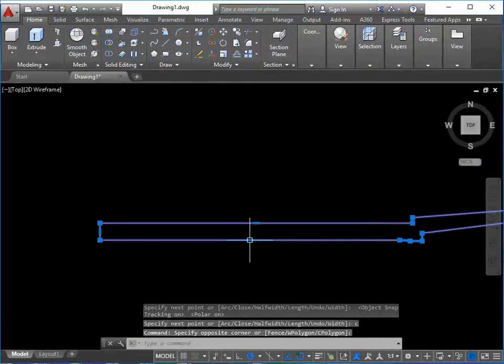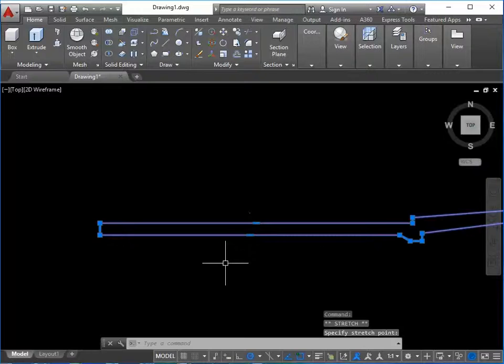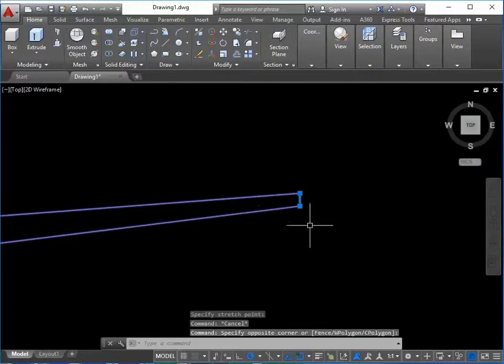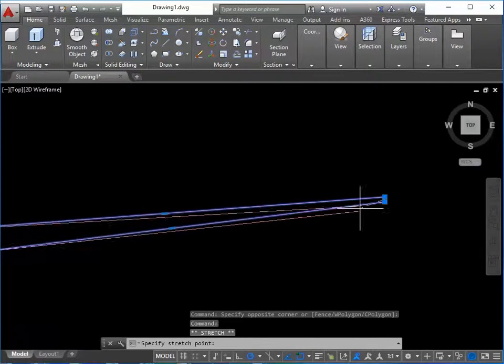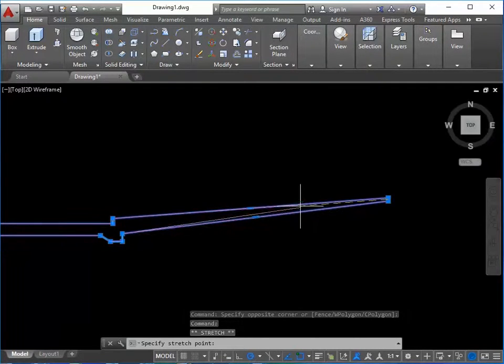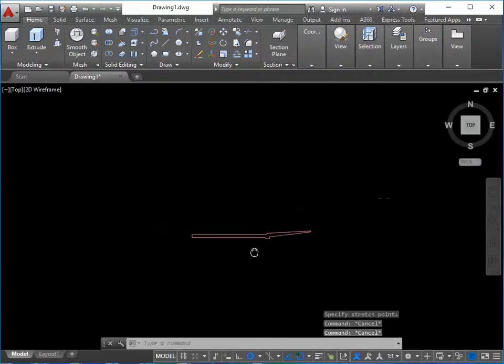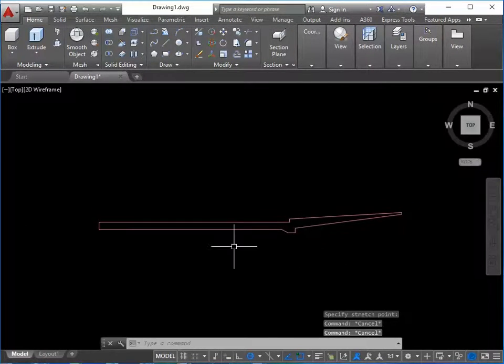Let's raise that up a little bit. I'll just grab the polyline and stretch that up to narrow that a little bit. So this surface that you see here is going to become the actual plate shape. And since this is a polyline, I can of course grab these edges and vertices and change the location of that. So I'm pretty happy with that. That's a cross-sectional shape for the plate.